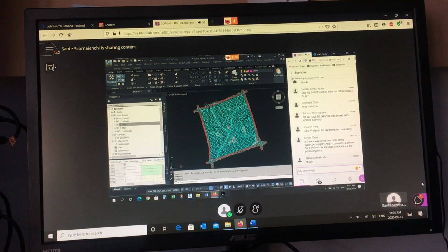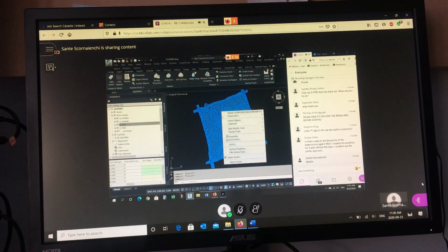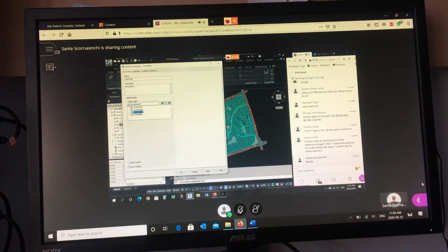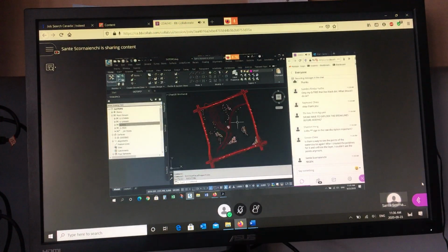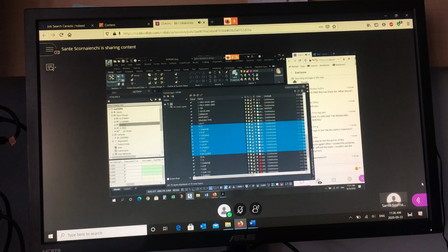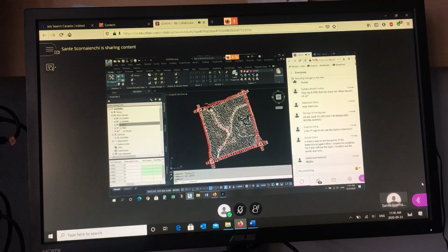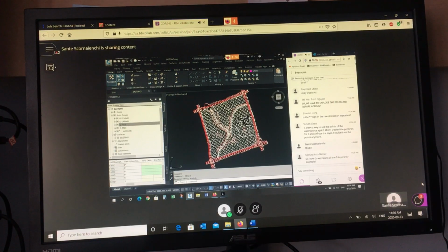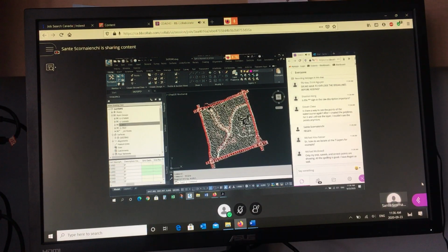Watch this. I'm going to turn off my layers. I'm going to get rid of the surface so it's not there. So no display. Remember I froze all my P layers except for a few? I'm going to thaw them. I'm going to go to P, take all my P layer points and thaw them, right? So now they should all be visible. When I go back to my drawing, if you don't see them, if they don't appear, type in regen. And that's just the video card playing tricks on you. Sometimes they're off, and it's just one way of getting the view back.